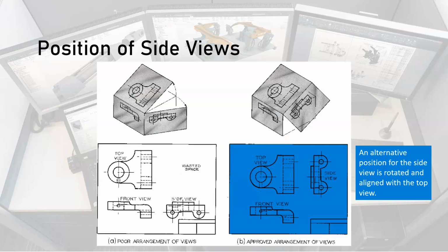Okay, so how we unfold the glass box is kind of dependent on the geometry and some other circumstances. So here we have an unfolding of the glass box where, if we call this the front view, the hinge is between the front view and the right side view. And you can see what happens here is the right side view unfolds, and it's really close to the title block, right? And then we have a lot of wasted space up here.